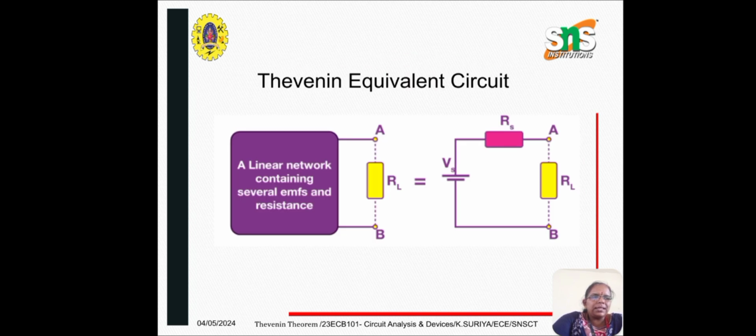So this is a Thevenin's equivalent circuit. As shown here, a complex network will be replaced by a voltage source in series with a resistance, and you will be connecting the load resistance as shown here.